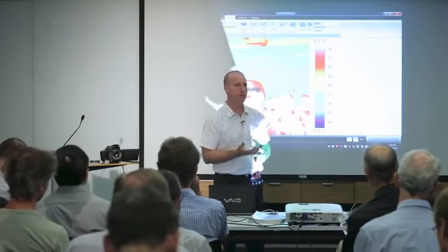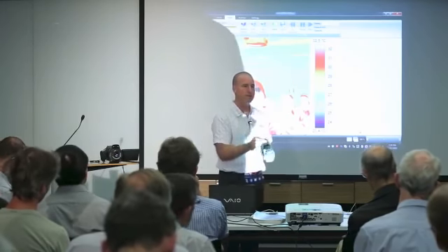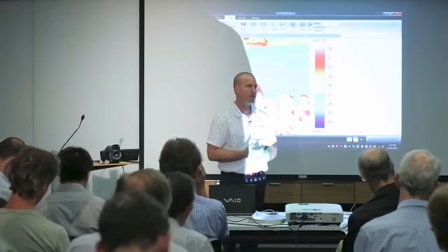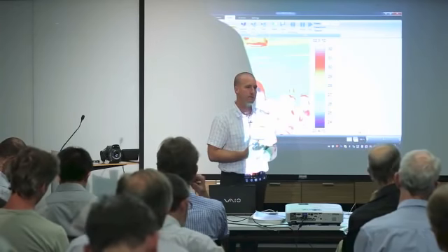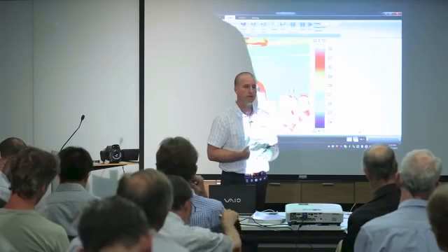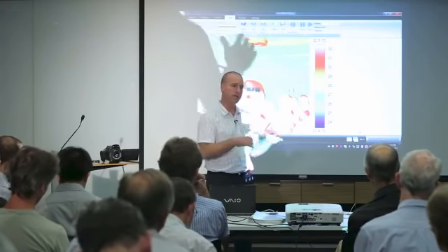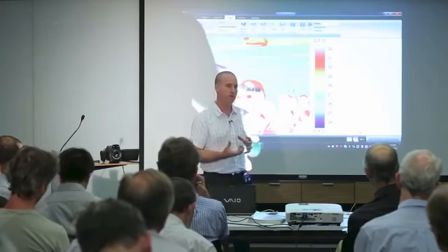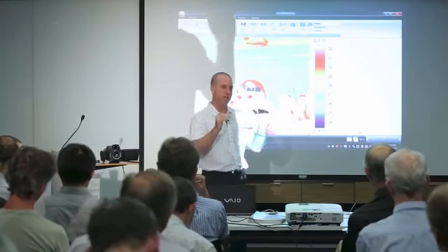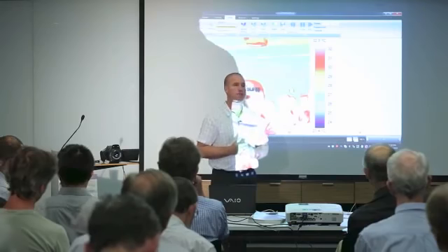At my place, I've got the M51, which is the middle weight, middle temperature, in the upstairs ceiling, and for 7 months we haven't used an air conditioner or a heater. Not once. Don't need it, because there's enough cold in the night to release just by opening windows, and there's enough heat in the day to charge it to keep it warm at night. So just by managing those two things, you can actually get rid of a lot of heating and cooling loads that you'd normally pay for.